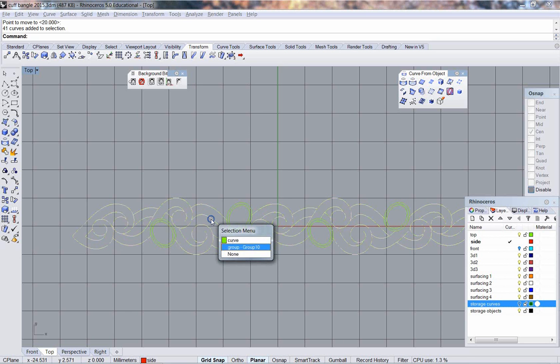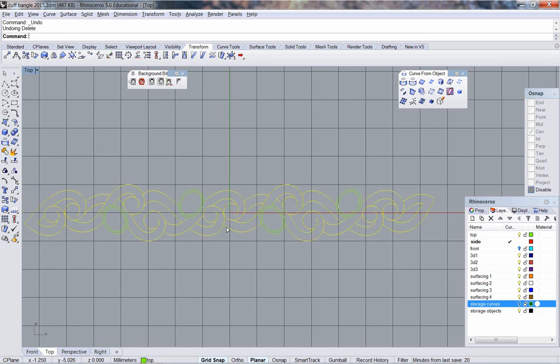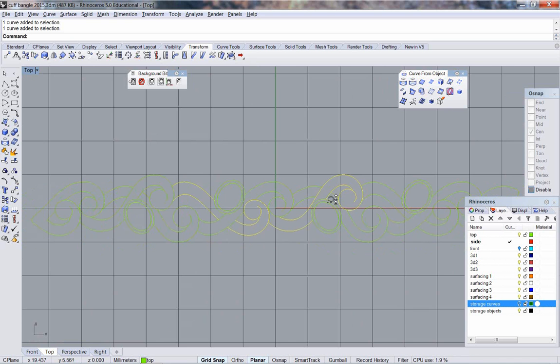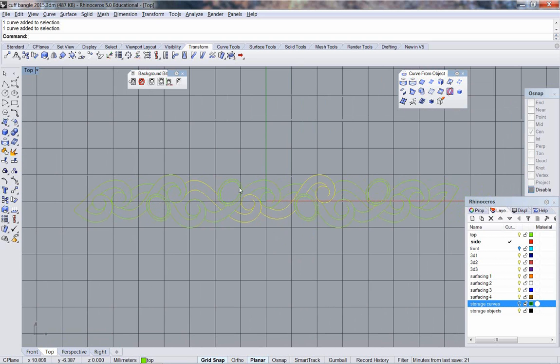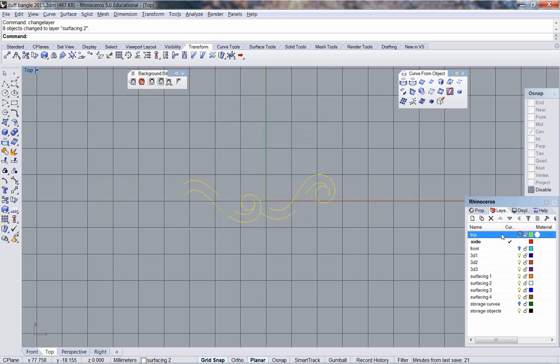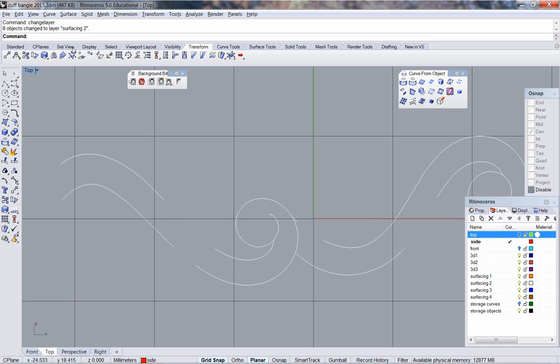Okay, I have two things here. Don't want that. Alright, duplicate information. My repeat runs from here to here. And that just continues down. It does something a little different at the ends, but for now this is good. I'm going to Control C, Control V, put it on a new layer, turn off my green layer, and reconstitute this as something I can actually make a drawing with.